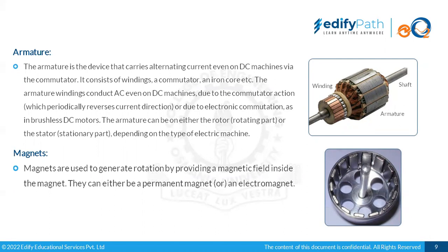Say if we are constructing a 1 kilowatt motor, if it were made with normal ferrite magnets, the size would be 4 times larger than what we see today, the 10-inch or 12-inch diameter that we see. But thanks to these rare earth magnets, a more powerful motor can be constructed in a smaller space.